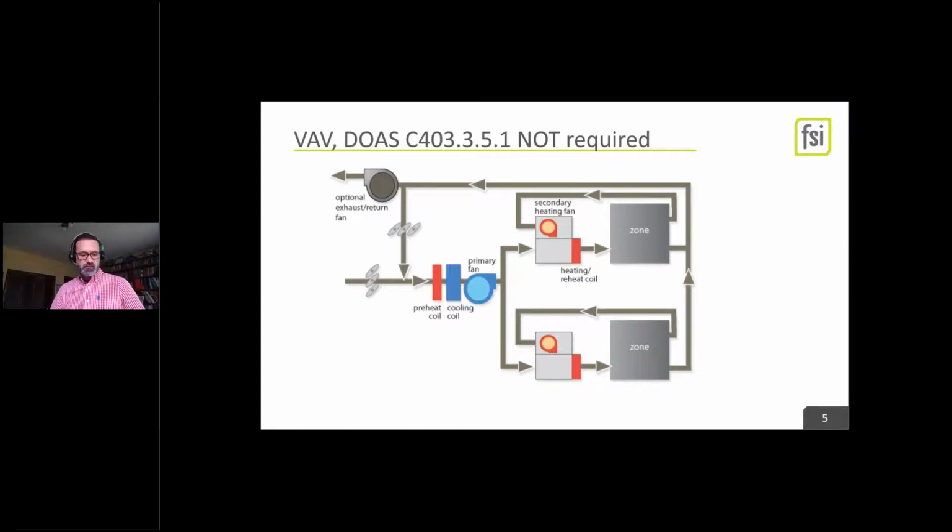Okay, so VAV systems, you might need to do a heat pump on the rooftop, and you are allowed to have electric reheat in the boxes. Of course, Washington is going to allow you to just keep terminal units the same. There is a provision even in the Seattle code, the current way it's written, that you get some electric heat for heat pumps for low temperature ambient operation.